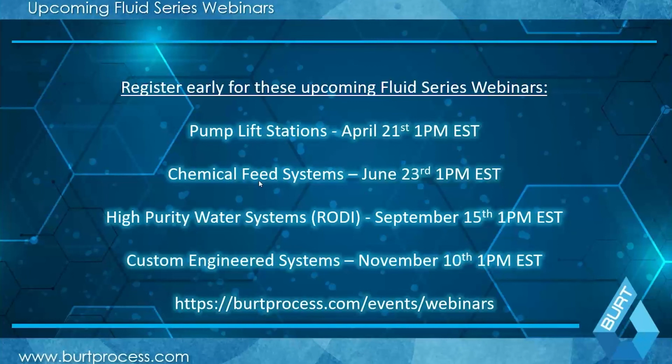And so long as you know what the flow rate is coming into your system, you can size it appropriately. So there isn't per se a limit in the system to that. Again, if it's going to be more of an intermittent high-level flow, you might want to look at putting in an equalization tank in those cases.